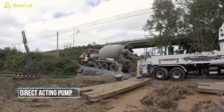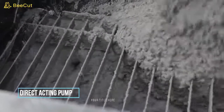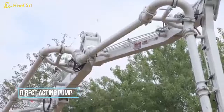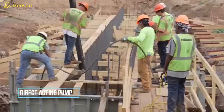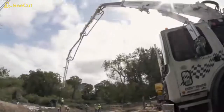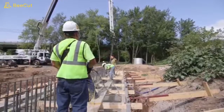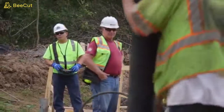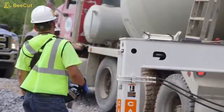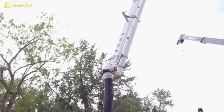Next, direct acting concrete pump. The operation of the direct acting pump is simple. The concrete is fed into the pump by gravity and partly by suction created due to the reciprocating motion of the horizontally acting piston, while the semi-rotary valve opens and closes alternately. Ideally, the diameter of the suction pipe should be at least 3 times the maximum size of the aggregate in the concrete to be pumped.